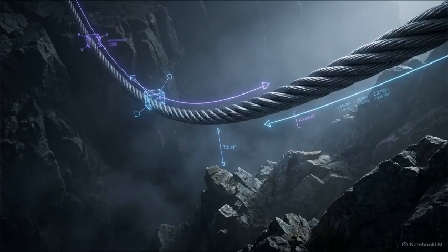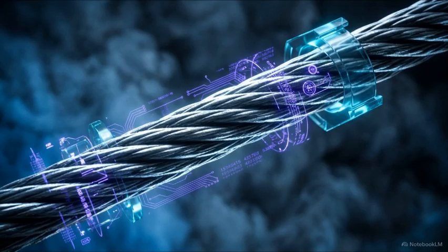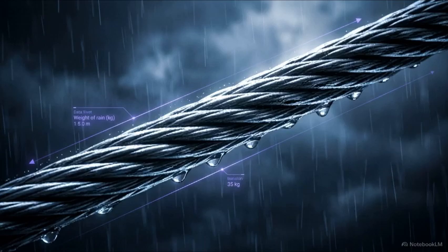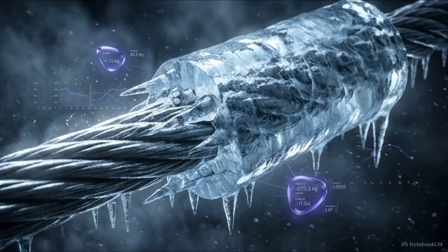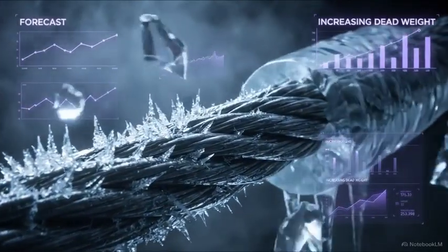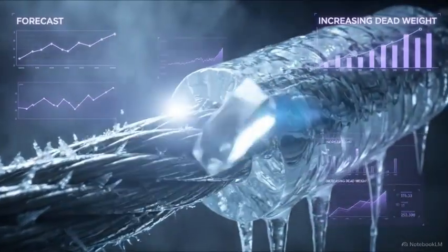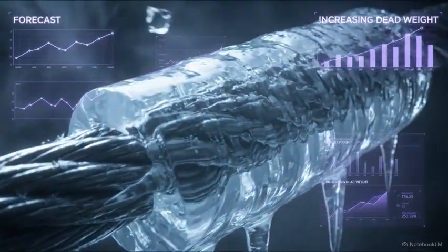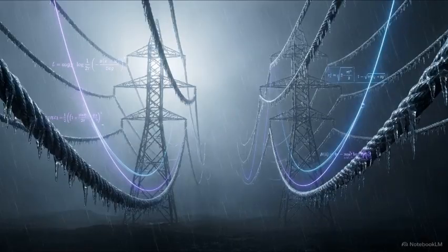Tracking that lowest point mathematically prevents thousands of pounds of electrified metal from dragging through the water or clipping a hillside when navigating extreme terrain. Out in the open atmosphere, the physical weight of the wire is constantly changing. In freezing conditions, a heavy layer of ice builds up entirely around the conductor. This adds direct vertical dead weight, pulling the cable further down toward the ground.